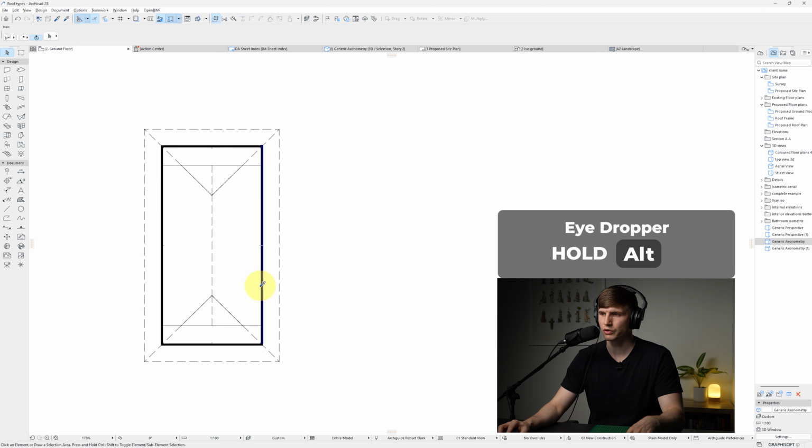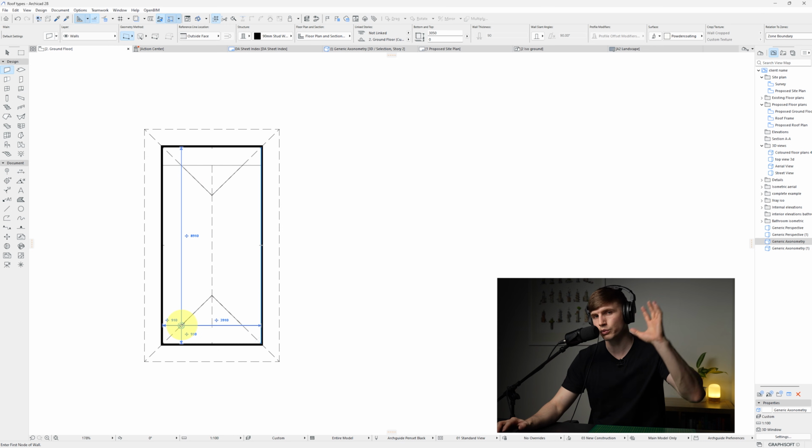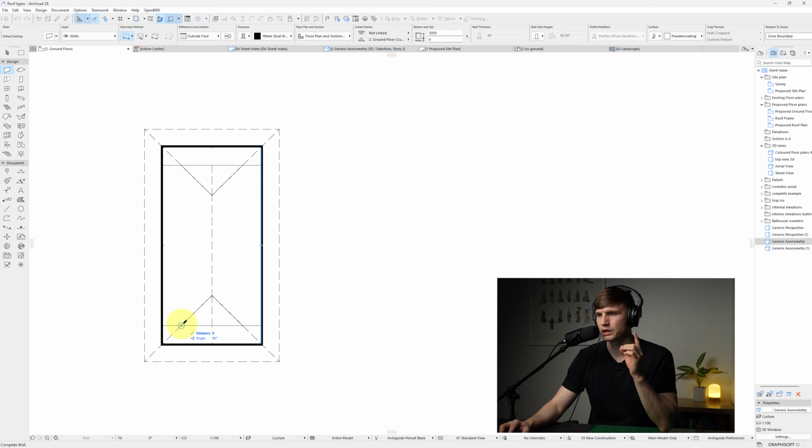We're just going to use one of our existing walls just here, say a 90 stud. We'll click where the roof intersects just here, and we'll drag our mouse all the way until we get that little X point, and we'll click again on this one just here. Do the same thing for this side just up here. We'll click once, and before I click again, I'm going to flip it around just so that it's facing inward. We'll click once more.